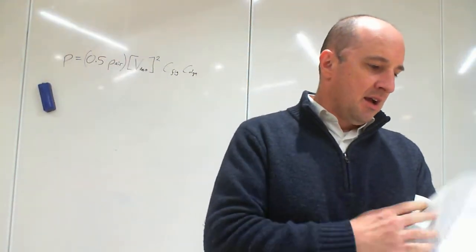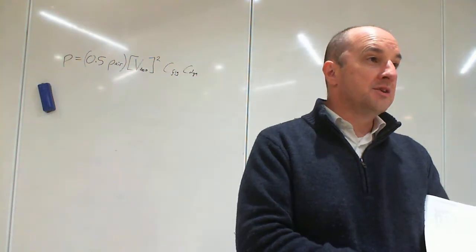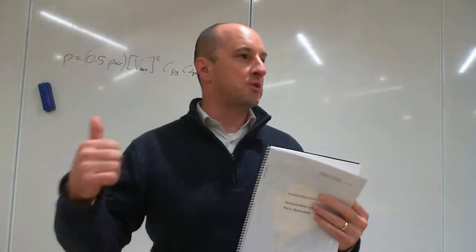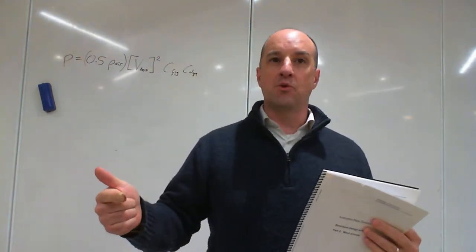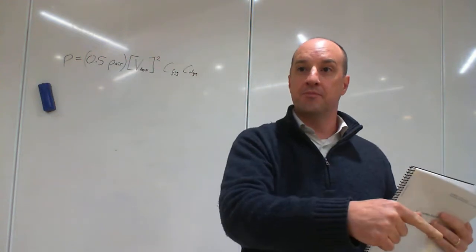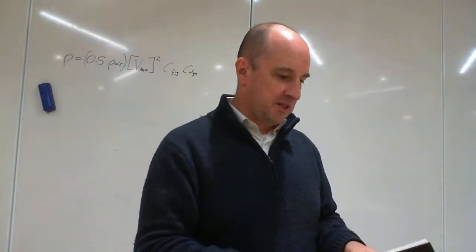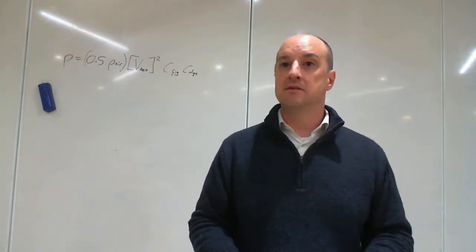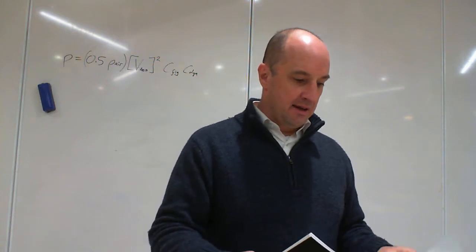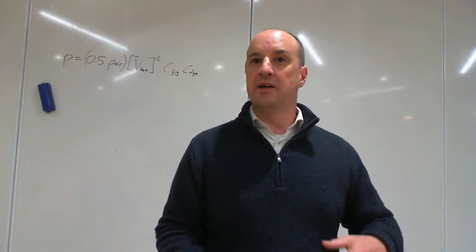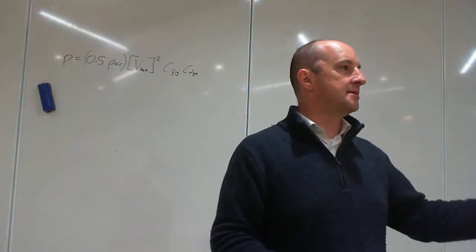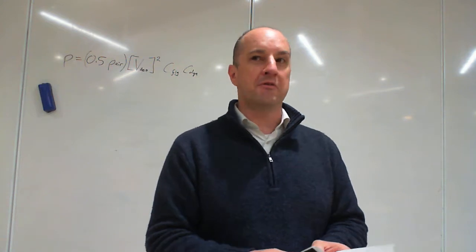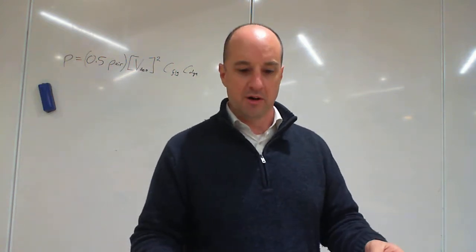Okay? So what we're going to do is work through this code. It comes in two parts. The first part is working out what the wind speed is. And the second part is working out what the wind does to the structure that you have. In order to get the wind speed, there's been a lot of data collection over decades by the Bureau of Meteorology, and they've collected wind speeds all over the country in all sorts of different circumstances and done statistical analysis on them all. So we can look up and say, if you're in a certain location, what's the wind speed you want.